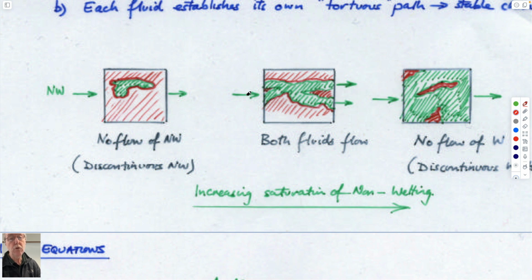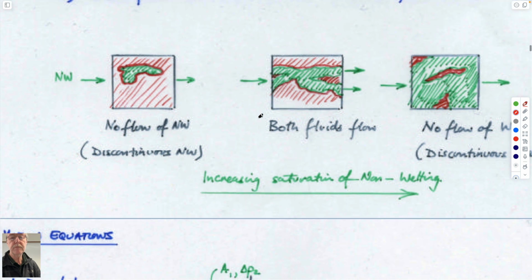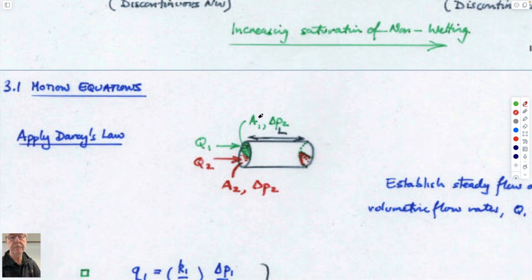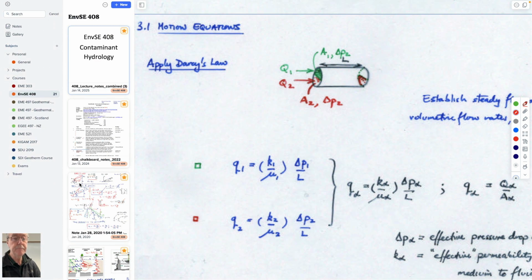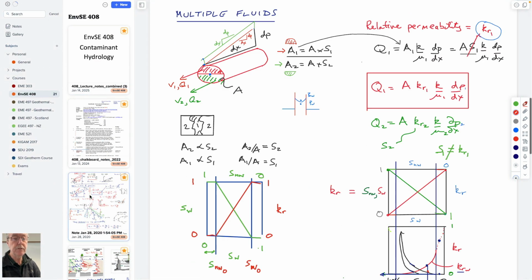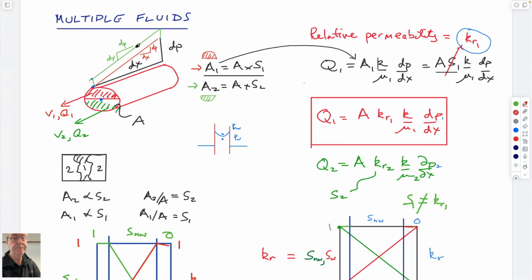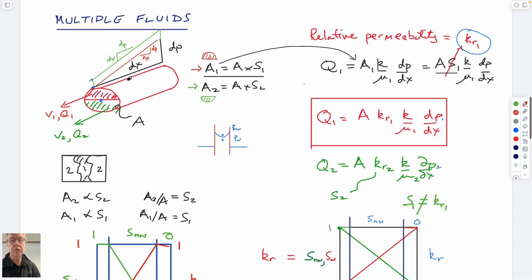If we keep on adding more green fluid than the red over time, then the green fluid would change the saturation. And at some stage, then the red fluid would not be able to flow from one side to the other. So that's the kind of process that we like to be able to follow. And so to do that, we'll try and divide the system into one where we centrifuge it down and we look at the behavior of those two fluids in isolation. So this is the thought experiment.